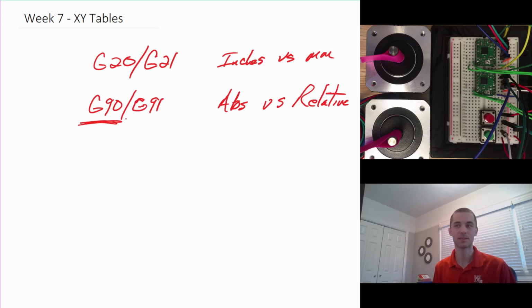Those essentially take that to the next level, right? You could have multiple different coordinate systems for your machine. And there could be reasons that that would simplify how you process either the machining or printing of particular features. There's also canned cycles, which are essentially combinations of a bunch of other G code commands.